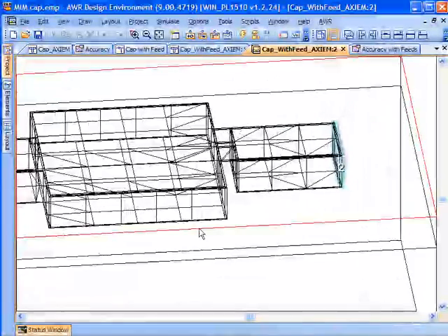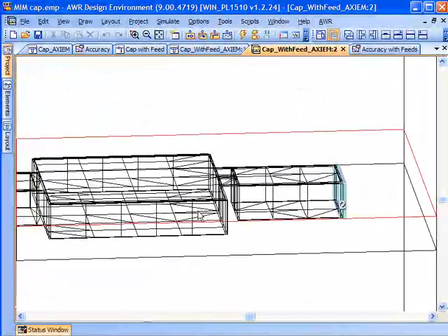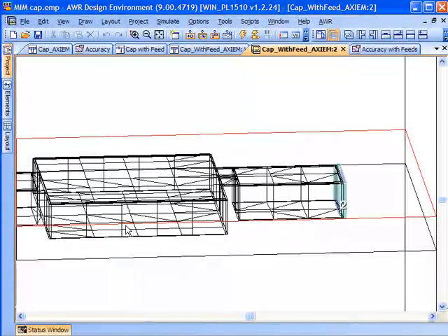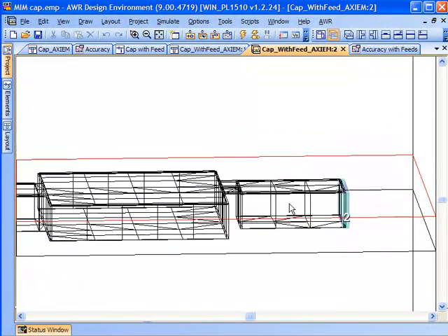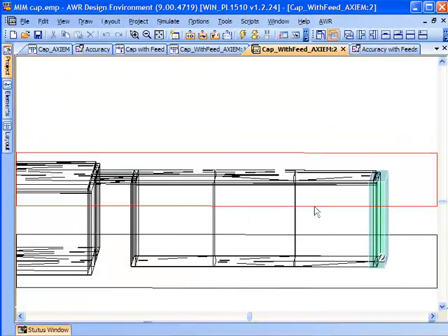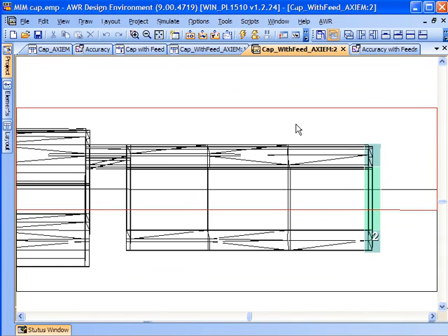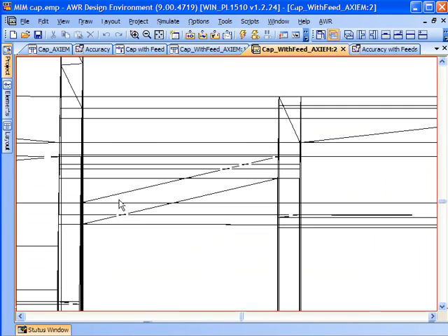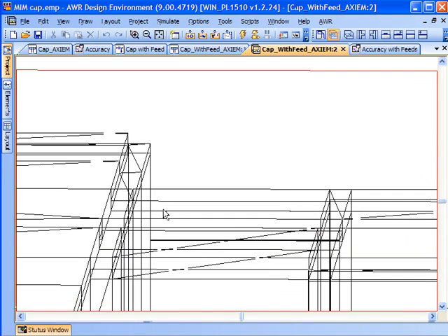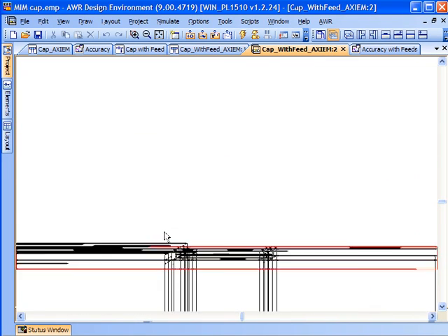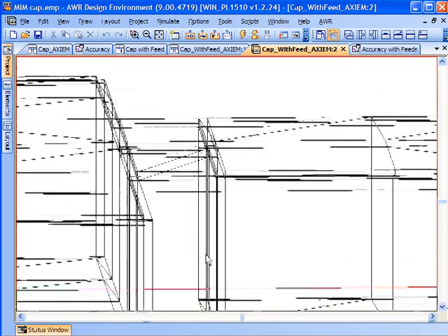First of all, we're using the 3D capability of AXIEM, both in terms of measuring the MIM cap itself, but also in terms of measuring the metal. Here's that microstrip line. We're using a thick metallization in the Win process where it's actually going to stack up those metals, and you can see that we're actually meshing in 3 dimensions. These sidewalls here are going to be calculated, and we're going to get the fringing effects of having that thick metal. But if you also look at the air bridge itself, you can see that we're meshing that in 3 dimensions. Let me zoom out a bit and we can get a better look at that. You can see that we're also going to mesh that in 3 dimensions.